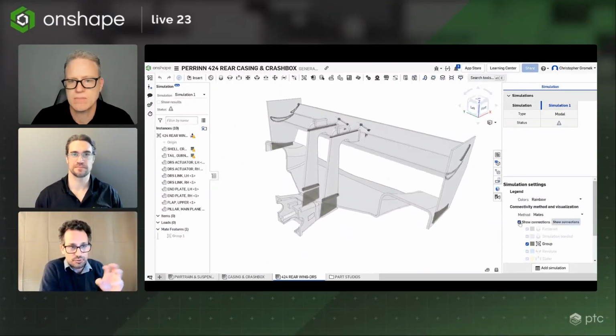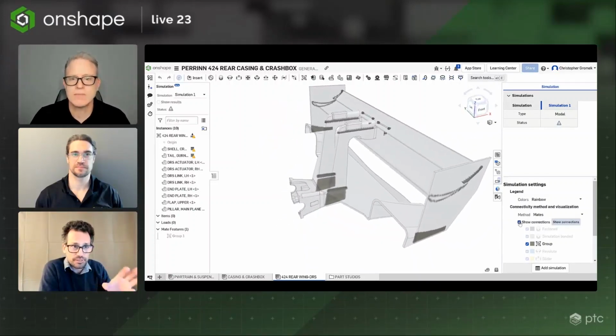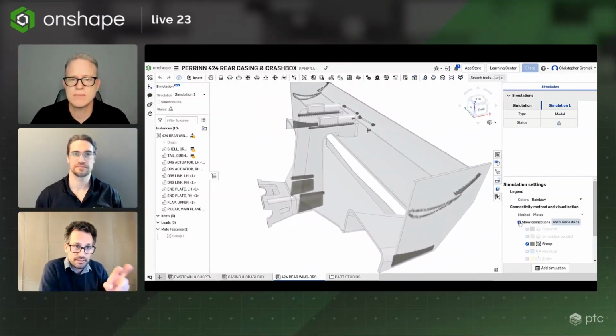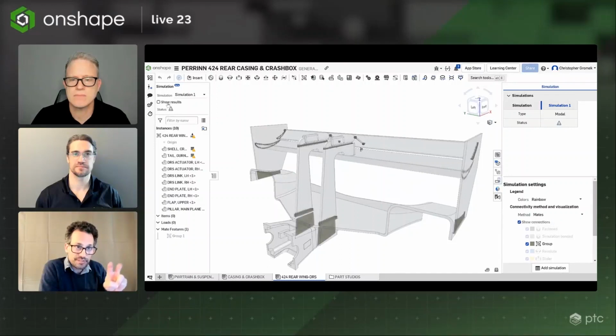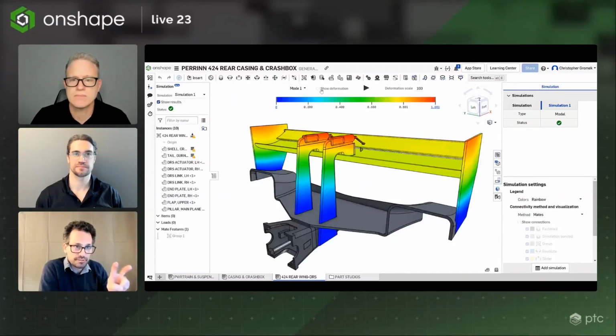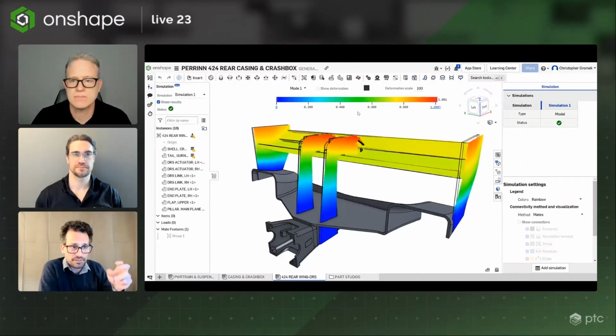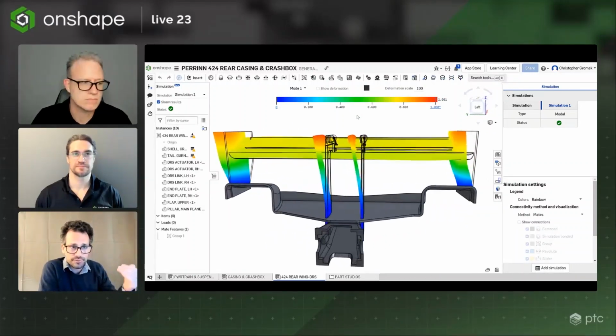We are switching to another assembly of the car, the rear wing. You can see the two pillars, the DRS system on top, which is 2 pneumatic actuators that will open the flap in a straight line to shed a bit of drag and go faster.